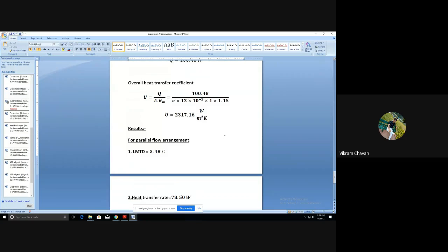If you perform that, then you have understood this particular chapter completely, because both things are important in this heat exchanger. You should know how to calculate the logarithmic mean temperature difference if all the temperature conditions are known, and you should know the effectiveness-number of transfer units method to determine the unknown temperatures.